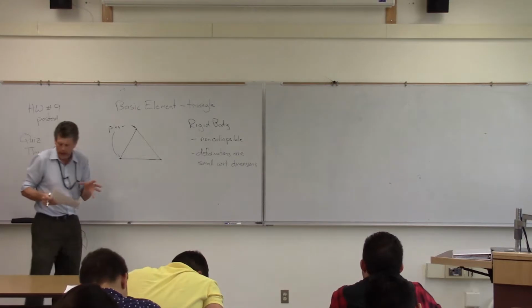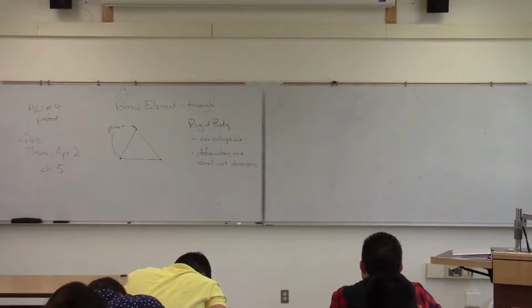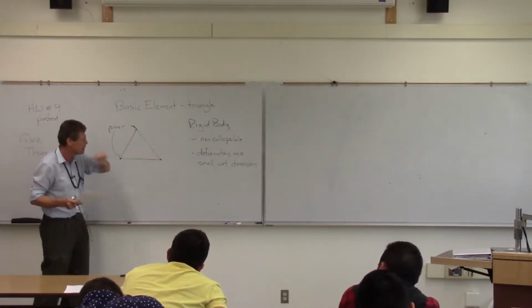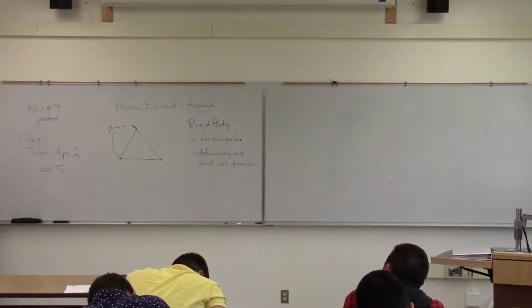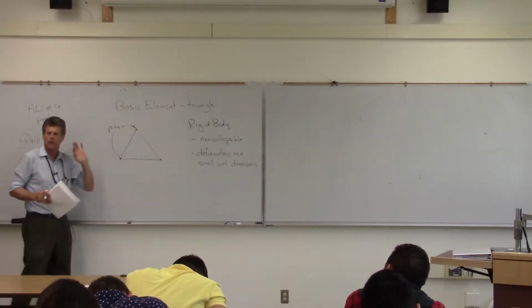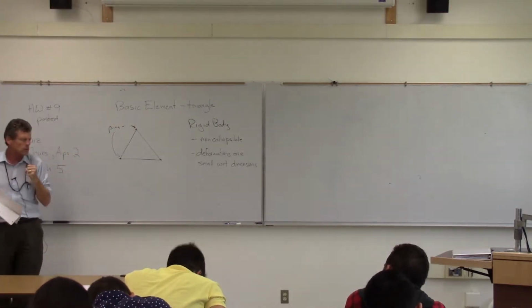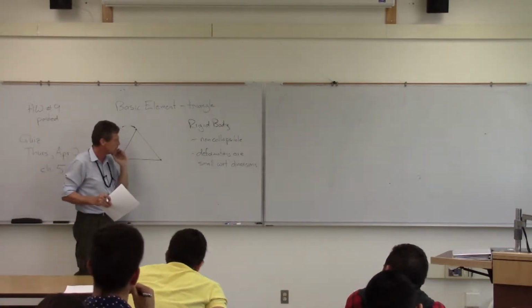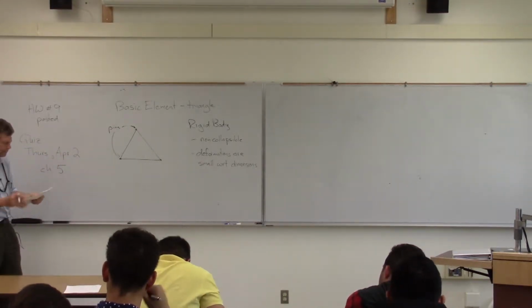And then it meets our static definition of a rigid body, not the guy that works out in the gym, but the deformations of any of those pins when we push or pull on it and that sort of thing are going to be small with respect to, my little abbreviation there, WRT, the dimensions of it. So when we think about that, this is going to be in feet or meters and that sort of thing. And when we consider the deformations there at those pins, we're probably talking less than an inch and maybe down into the millimeter stage in terms of the SI system. So it meets our definition then of a rigid body.